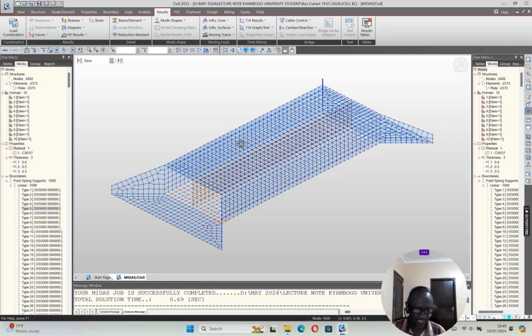If I am to generate the pressure, first of all, the live load surcharge: if I'm using HB45 or a compactive roller of 20 kilonewton per square meter as the surcharge, then because of the at-rest coefficient of 0.5, the surcharge going down uniformly would be 0.5 multiplied by 20, and I get 10 kilonewton per square meter as my live load surcharge.